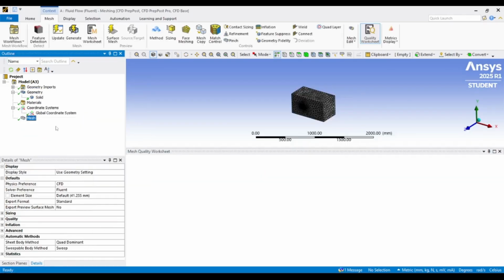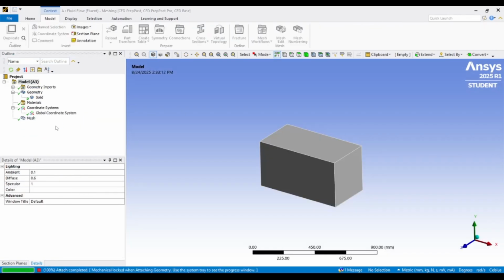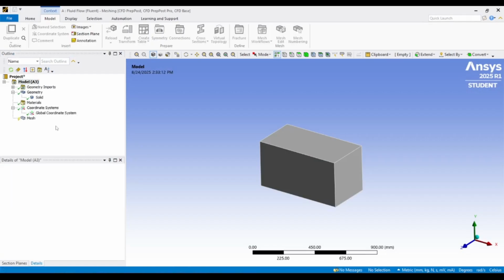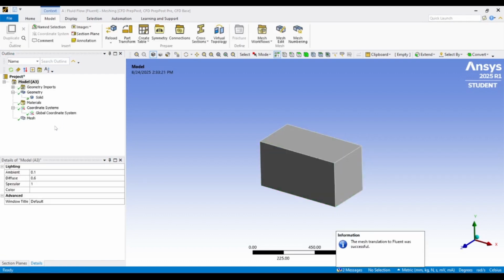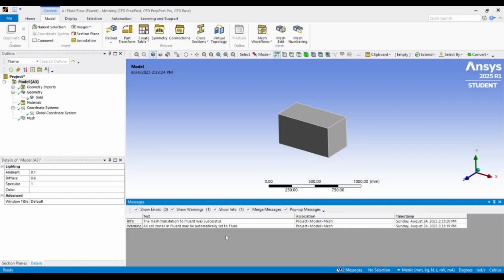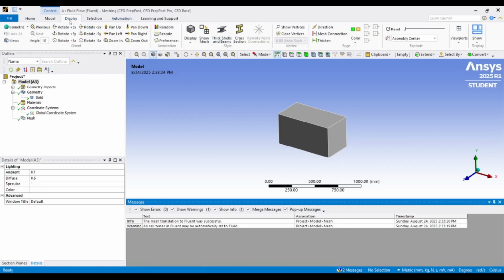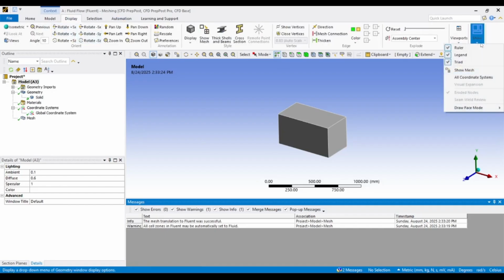Once you set that, define the total simulation time to cover multiple vortex shedding cycles, typically around 10 to 20 seconds of physical time depending on your flow speed and domain length. To capture the transient effects properly, enable data sampling for time statistics under the Calculation Activities tab, so you can average pressure and velocity over time later.